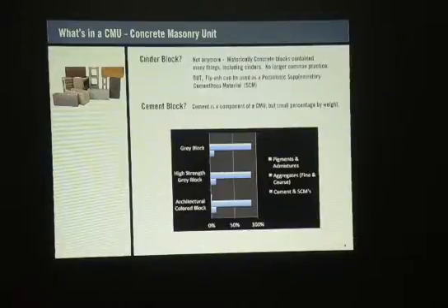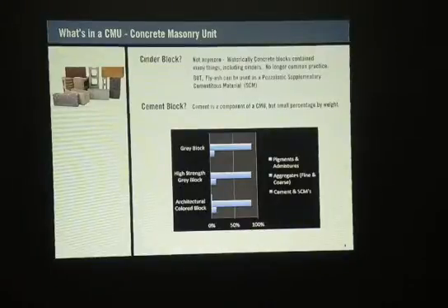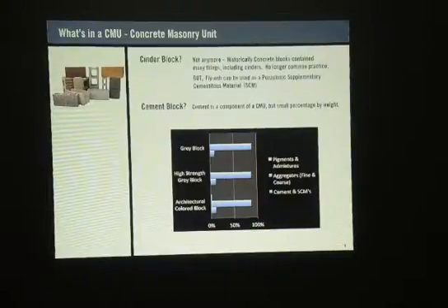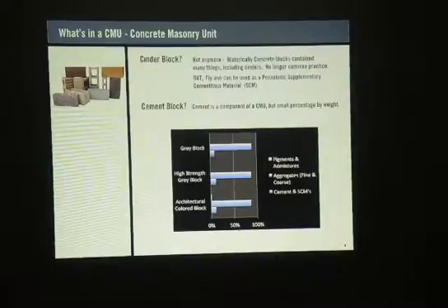And the other thing is condensation, okay? If we don't have good air barrier systems and we have weeps, okay? Last year, again, I was talking about waterproofing. If we don't have weeps at the bottom of our stucco, we're going to have problems and issues with mold and mildew and bacteria getting trapped. And then what's going to happen is we're going to see a paint or a coating that's going to start to discolor. And then it's going to start to get worse. It's going to start to peel and chip and crack.